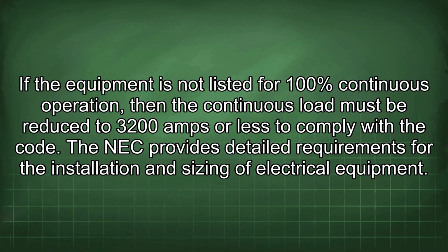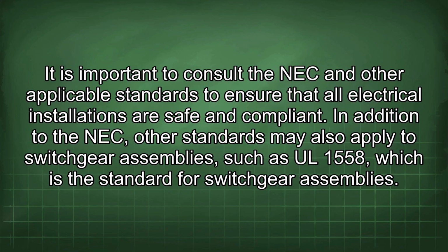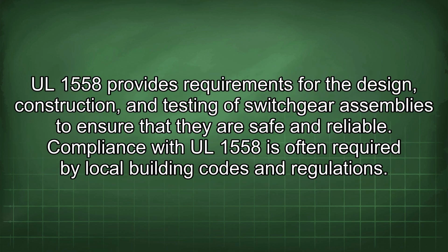The NEC provides detailed requirements for the installation and sizing of electrical equipment. It is important to consult the NEC and other applicable standards to ensure that all electrical installations are safe and compliant. In addition to the NEC, other standards may also apply to switchgear assemblies, such as UL 1558, which is the standard for switchgear assemblies. UL 1558 provides requirements for the design, construction, and testing of switchgear assemblies to ensure that they are safe and reliable. Compliance with UL 1558 is often required by local building codes and regulations.